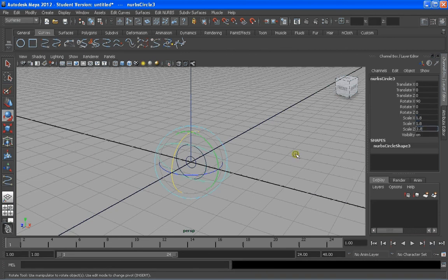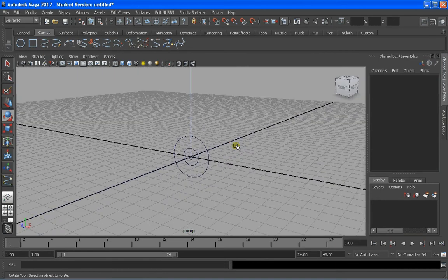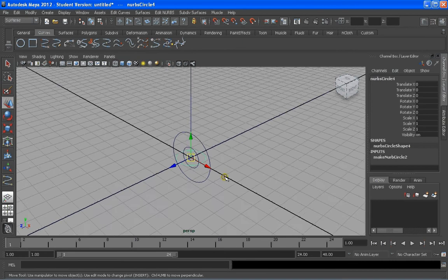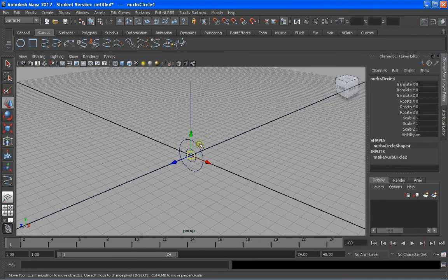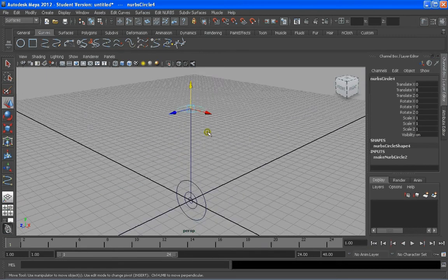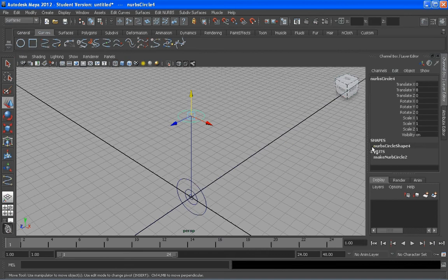We're going to create another circle here, one unit, and we're going to move it in W, and pressing X snap to the vertical grid that, even though we don't see it, is there. So 1, 2, 3, 4 into the 8th position, and we want this circle to be scale 1.4. Let's make it a little bigger, 1.6, and copy that as well.